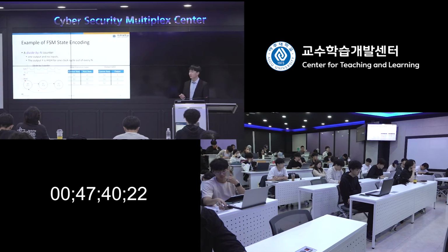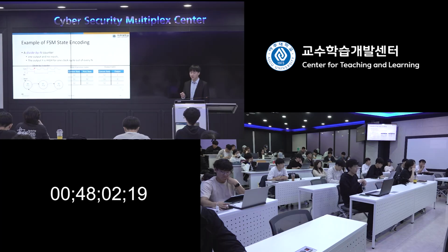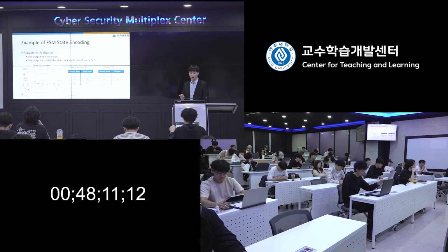In this case, we can build the state transition diagram. Since in this example we started from output y equals 1, we just start from this state, S0, where the output y equals 1. There's no input, because the only input is the clock itself. The clock triggers the state transition. So there's no information on top of the arrows, arcs, right?